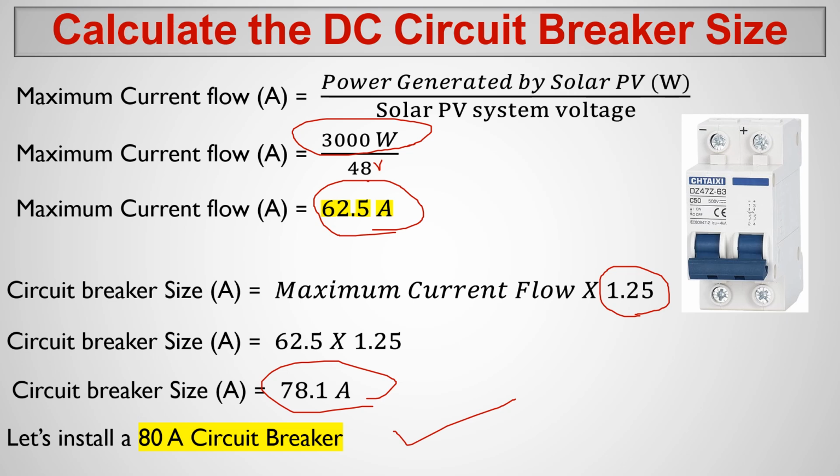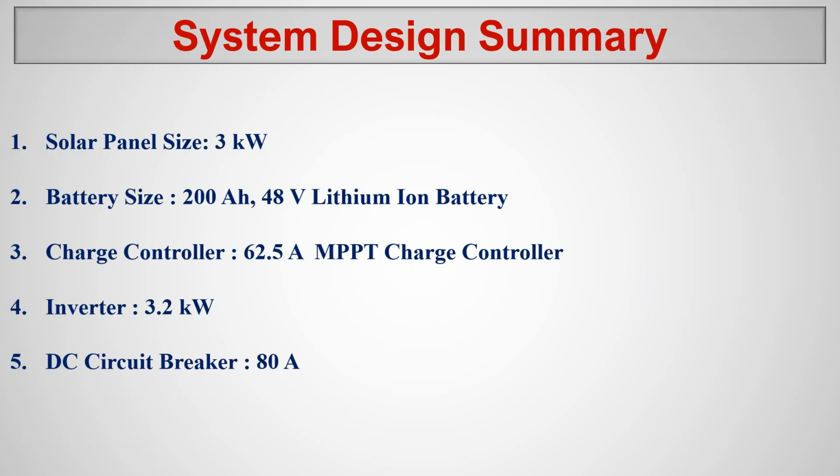If we get 1.525 times more than that, then something is wrong. A little more than that is okay; 5% more is fine. That is the logic. Even 10% more than the maximum rated current, what the manufacturer says, which will be 62.5 ampere. If we get more than that, that's a problem, and the breaker trips.